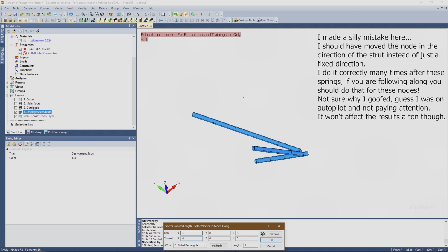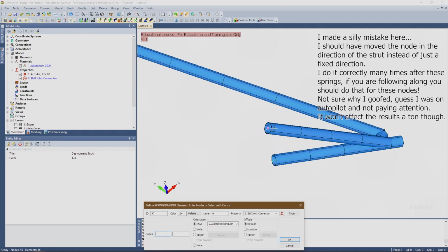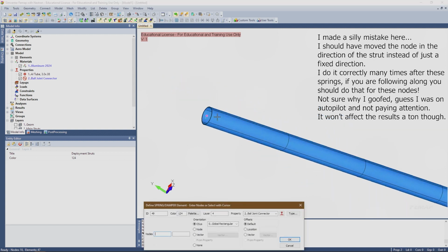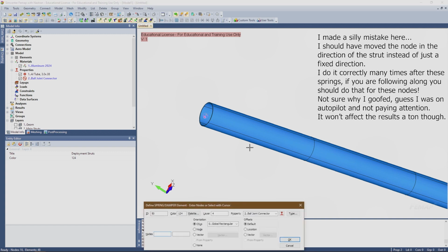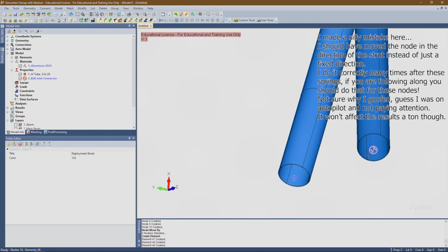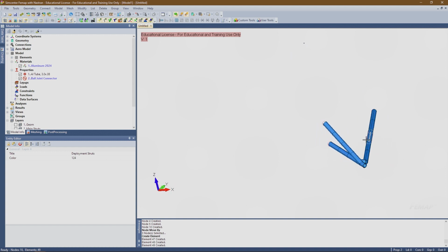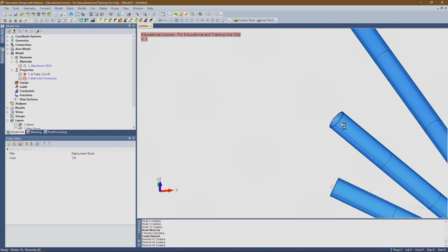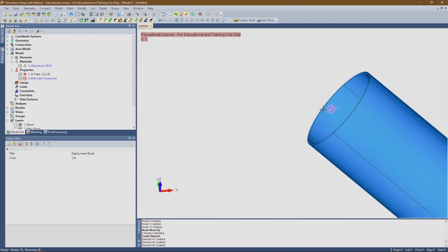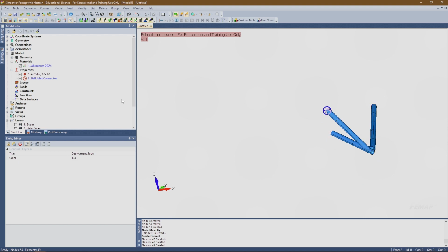And again, we just want to do the exact same thing. And then 0.5. Okay, great. And then model element. Like this. There we go. And finally, this guy. Okay, so now we've created a bunch of springs. These are essentially our joints to the lunar module. Like these are all of our bolted connections. So those will be fixed to ground with our constraint. We'll essentially fix this node to ground. I'll do that at the end when I have the rest of these elements. There's still some other model prep we need to do.